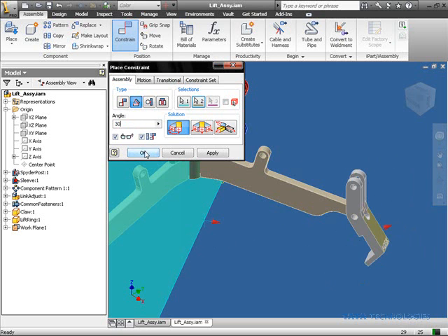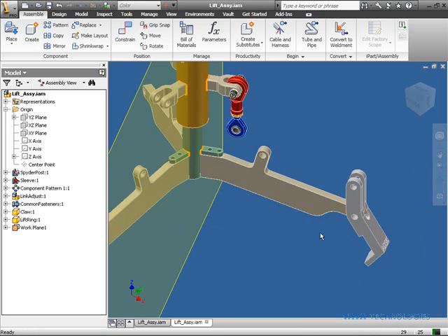I know this because I cannot click and drag it, and also when I click on the part and try moving it, I get that little symbol next to my arrowhead letting me know this cannot be moved. It is now fully constrained. I'm now done with my work plane, so just to clear up my display, I'm going to turn the visibility of it off.